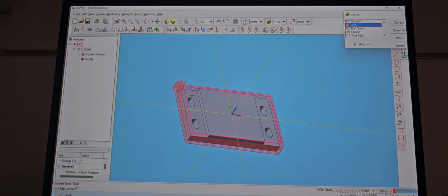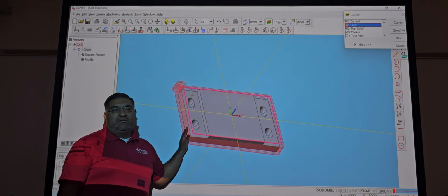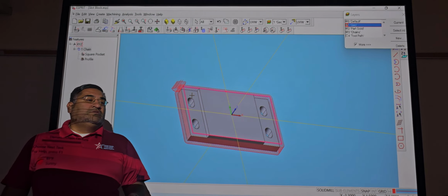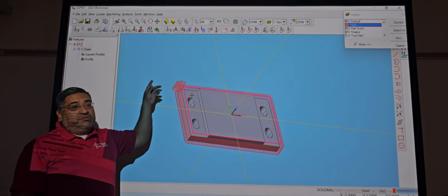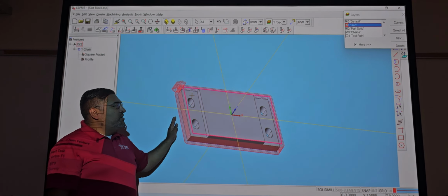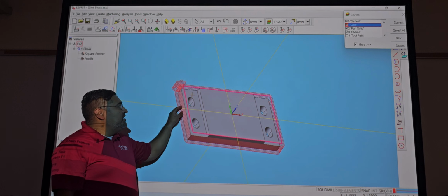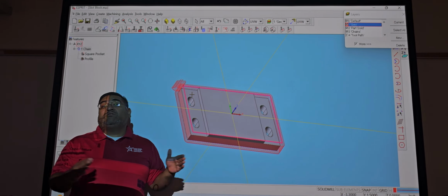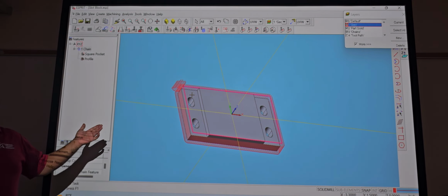Alright. So it was basically saying, hey, you don't have that much stock material, because it's up to your stock, right? So that's why it's not letting me do anything. Unless I increase my stock in my simulation, it wouldn't let me do it that way. Does that make sense? Because right now when this one cuts, it's not going to cut anything because we drew it already 2D. Exactly. So that's why that little code came out.